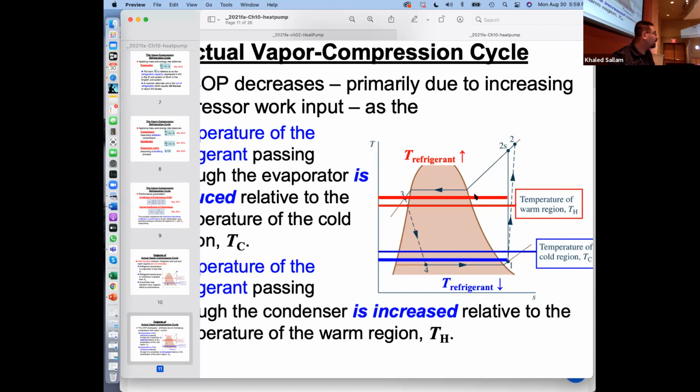On a hot day, you really have to sympathize with the compressor and realize that on this side, he has to go really high. So at least on the other side, don't let him go really low, right? Because that really long distance is a lot of energy. And you see what happens if I go lower and lower with my T_L? What is the bad thing besides the compressor going higher and taking more work? What else bad will happen to us?